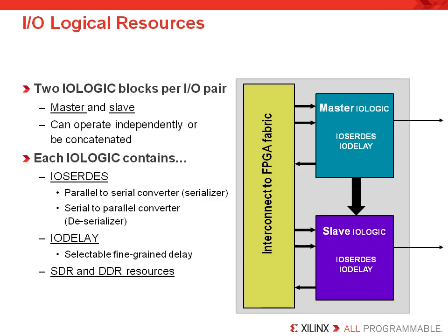Besides the register and SelectIO resources, there is also SerDes functionality built into each IOB. This includes both parallel to serial and serial to parallel conversion. This is a programmable functionality that can decode a wide range of signals. The O-SerDes and I-SerDes combination is probably one of the most useful and radical developments. Many issues that you would traditionally address by using the FPGA fabric are now handled within these blocks. Tasks such as training pattern recognition, clock-to-data alignment, and crossing of clock domains between high-speed serial I/O and slower parallel clock domains can now be accomplished with the dedicated logic included in the SerDes resources.